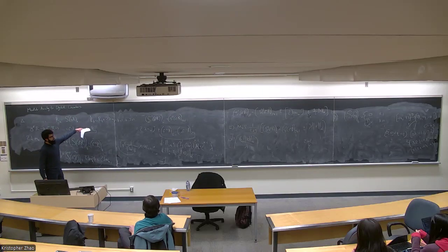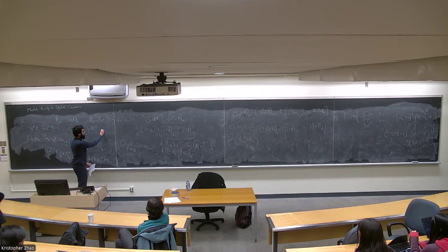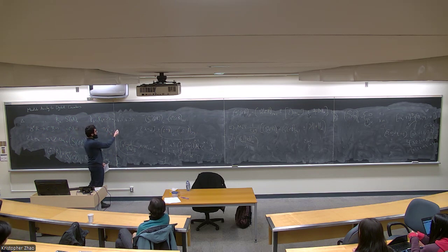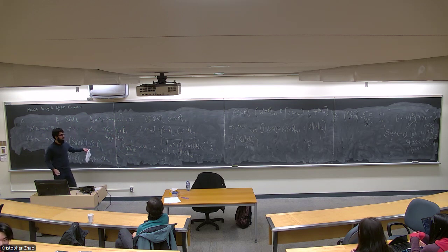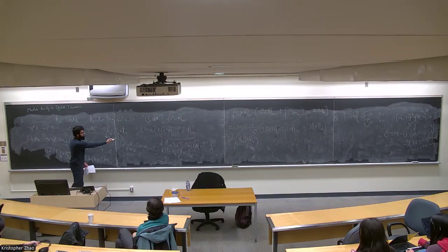So using this R hat, we can finally compute our X hat to be equal to the values that we know, yk, plus our estimated values over here, R hat k, and then this will just be equal to xk again plus some unknown constant. However, this unknown constant is not a big deal now, because even if you have the ground truth information for a single sample, because m remains the same, m is not a function of your index, you're able to recover that with only a single true value.